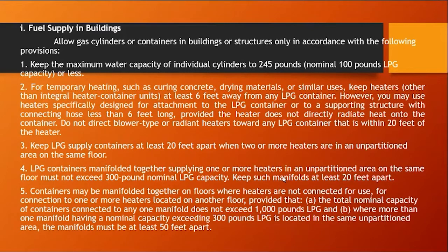However, you may use heaters specifically designed for attachment to the LPG container or to a supporting structure with a connecting hose less than 6 feet long, provided the heater does not directly radiate heat onto the container. Do not direct blower type or radiant heaters toward any LPG container that is within 20 feet of the heater. Next, keep LPG supply containers at least 20 feet apart when two or more heaters are in an unpartitioned area on the same floor.